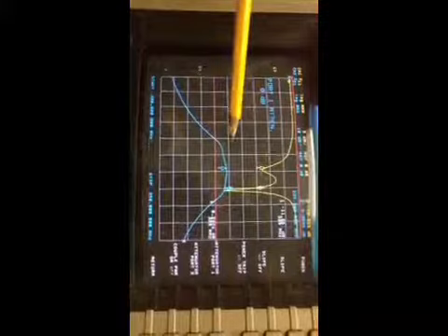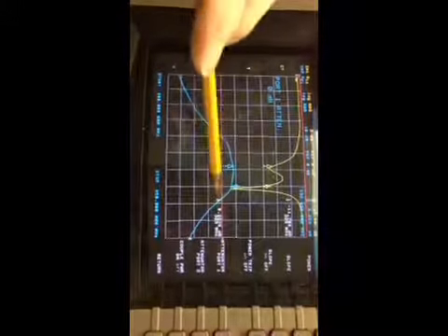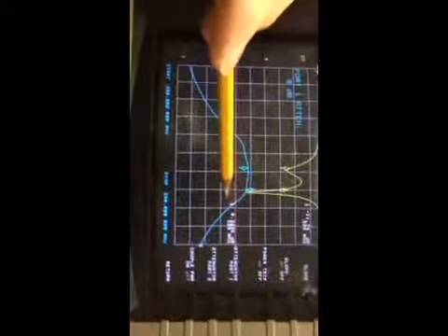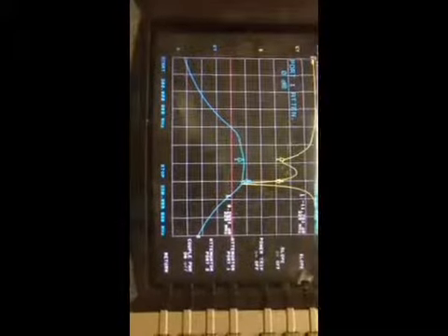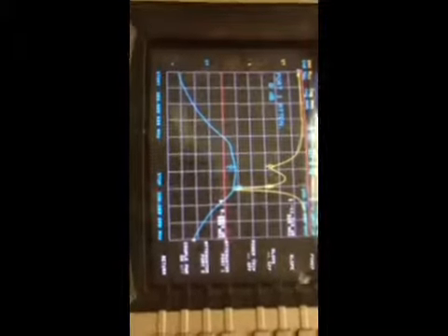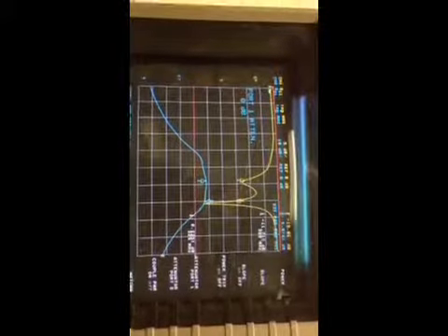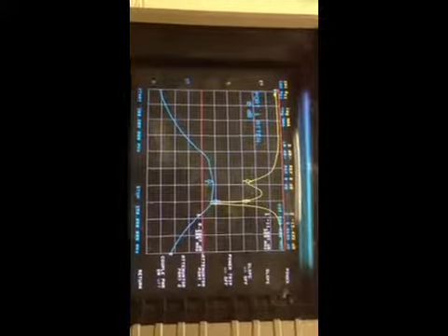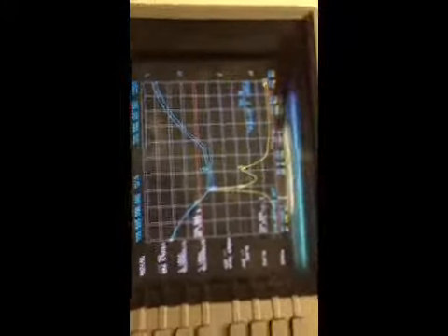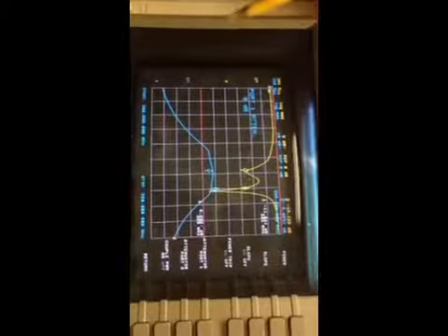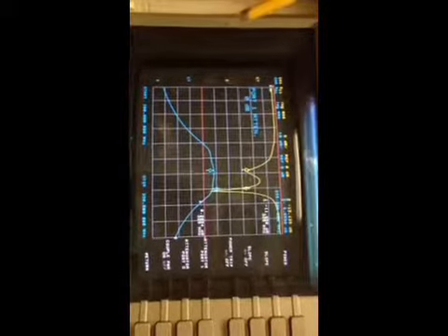So as you can see, looking at point 1, we are seeing 8 dB of gain on this system, which considering that there is a 10 dB amplifier in here, we're only seeing 2 dB of loss. At point 2, we're looking at 7 dB of gain, which, as I said, for a 10 dB amplifier, we're still seeing 3 dB of loss, which is within our specification.